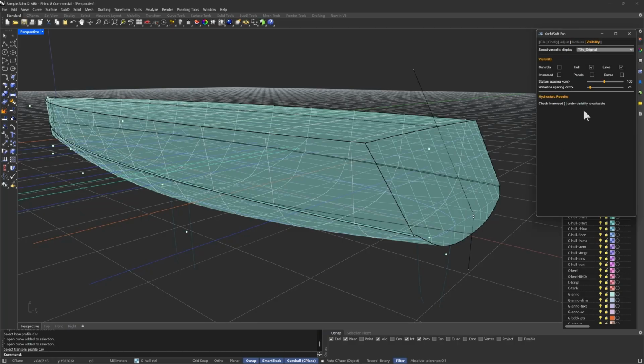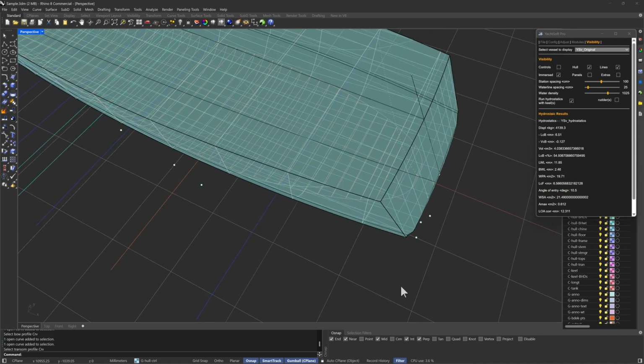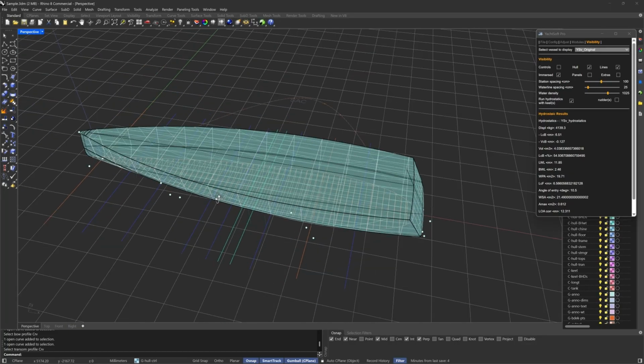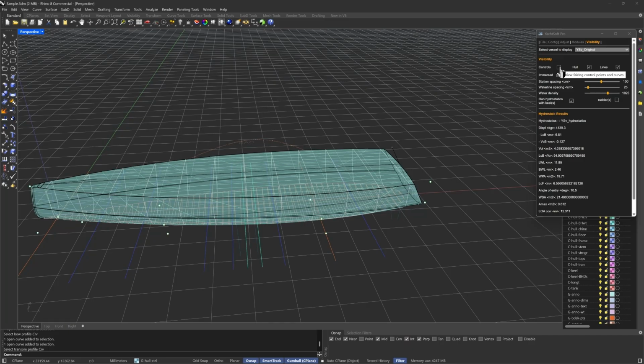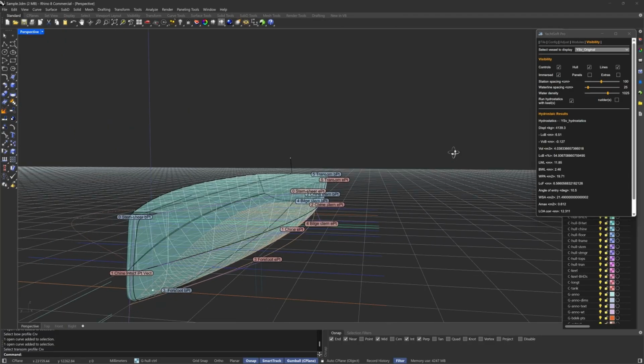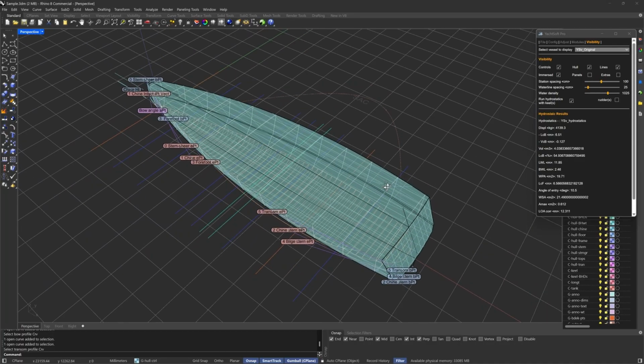At this point, if you want to get the hydrostatics, you would switch on the immersed properties. And this will obviously do a full hydrostatics of the boat to the datum waterline, which is the XY plane at the origin. It gives you a sectional area curve. And if you're confused about the control points, you can switch the naming convention on. So it basically puts a name on every point. And that is your vessel.